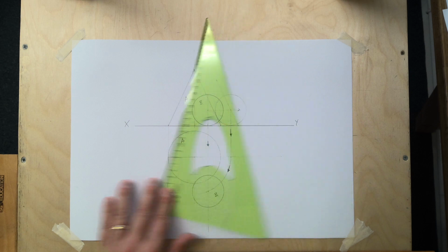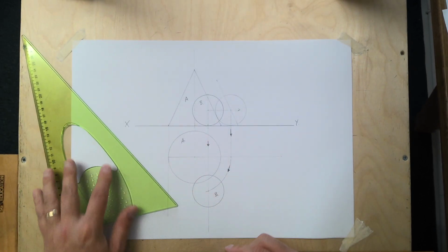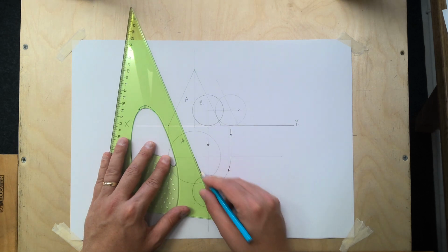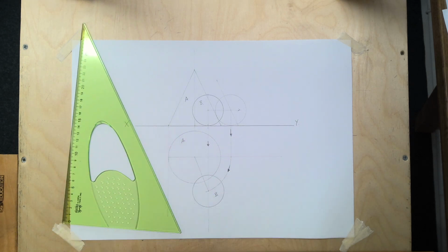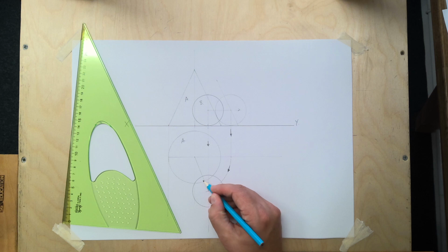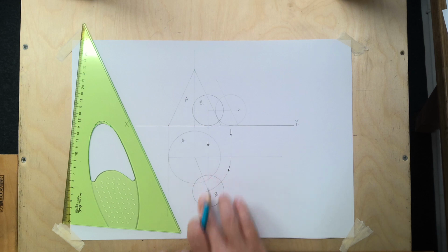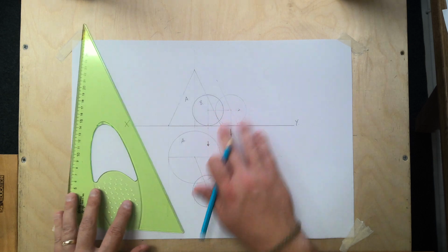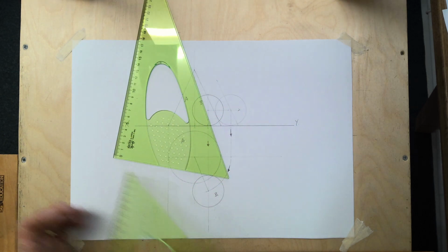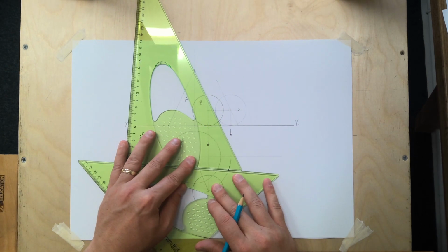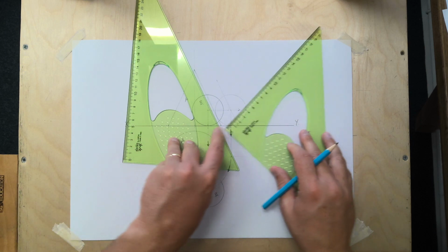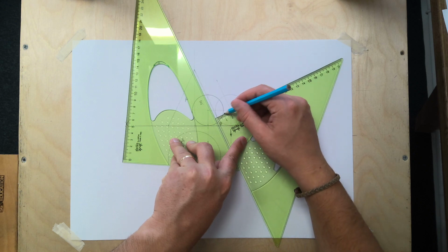Now, while we're here, we're going to get its point of contact. So joining the center points of two circles, that would be in plan. We know the point of contact is in here somewhere, so we can't find it just here yet, but we'll find it in a second. But we can find it up here in our elevation. So what you're going to do there is go perpendicular off the edge of the cone from the center here.